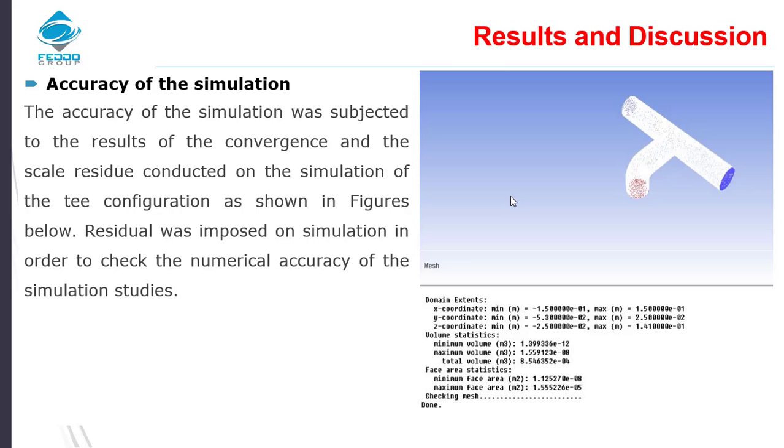Other software have their own ways of monitoring the imbalances, and these defects are commonly referred to as the residual of the system of algebraic equations. They measure the extent of imbalances, that is the extent of error arising from these equations, and terminate the numerical process when a specified tolerance is reached. That speaks a lot about how important convergence, residual and convergence tolerance are to general CFD simulation. That's why we are trying to reach this from the solution here.